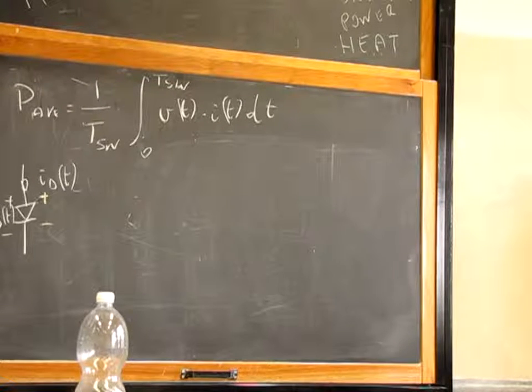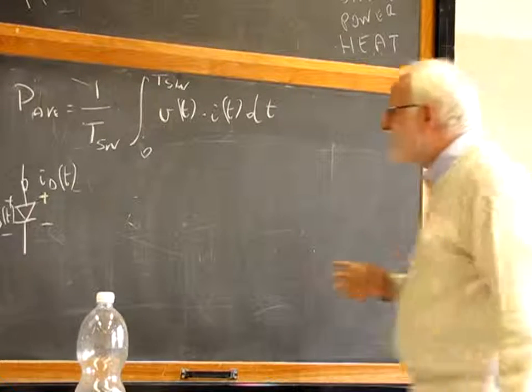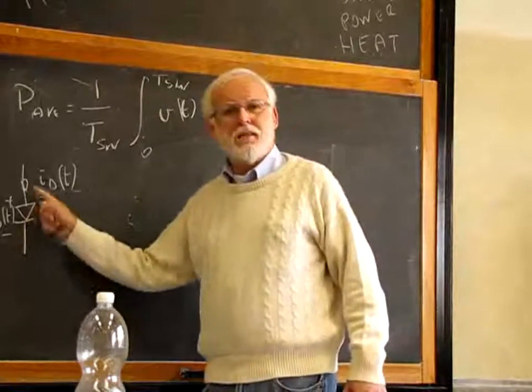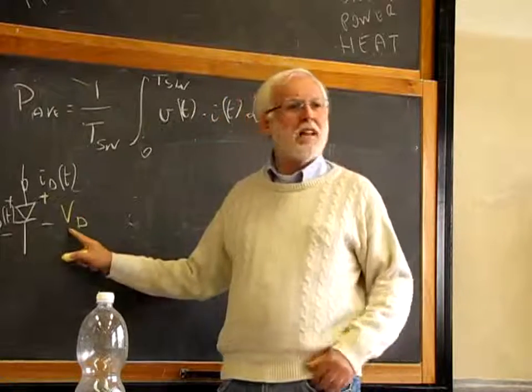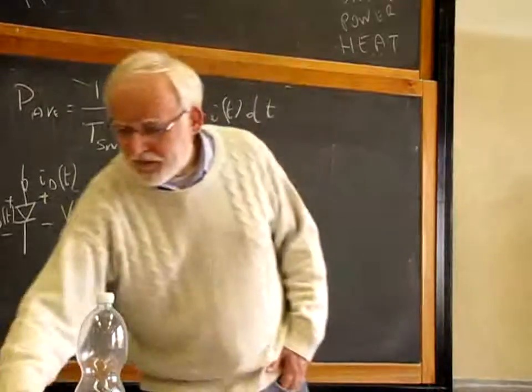If you have a bipolar transistor or an IGBT, when you saturate it, the voltage drop across a saturated transistor, VCE sat, is almost constant. The VCE sat for an IGBT is constant, could be a couple of volts or so. So there is a class of devices that have an almost constant voltage drop. And we can call this voltage drop capital VD, constant. And so you see that if you